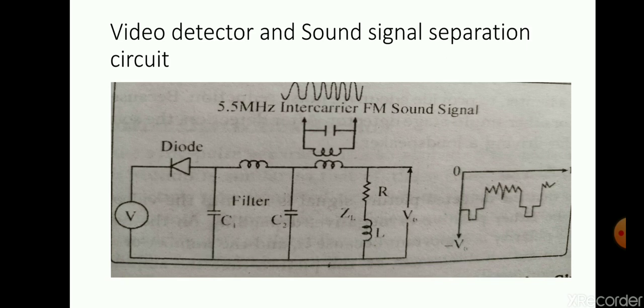A diode is used which is suitably polarized to rectify either positive or negative peaks of the input signal. An LC filter is used instead of the usual RC combination employed in radio receiver detectors. This is used to avoid undue attenuation of the diode signal while filtering.